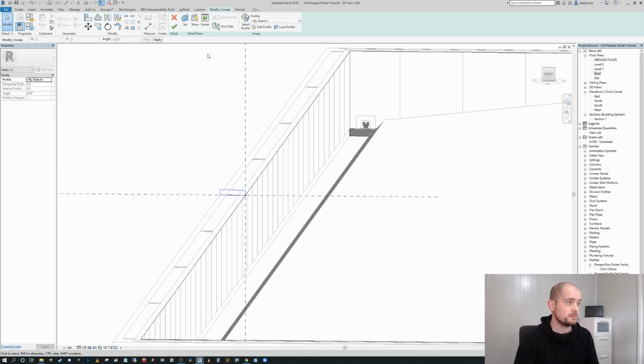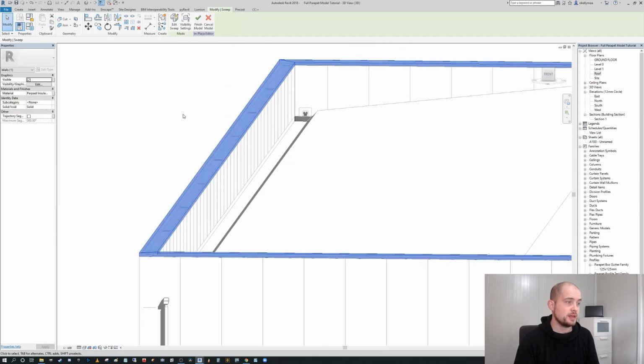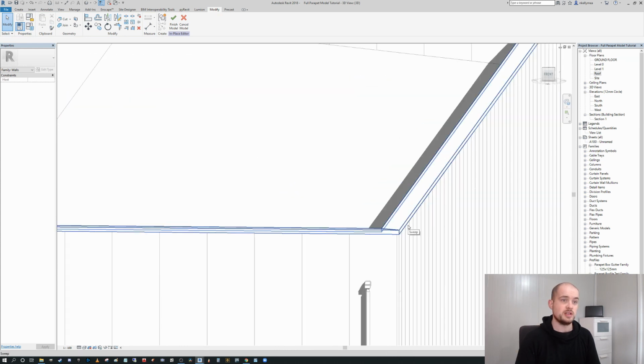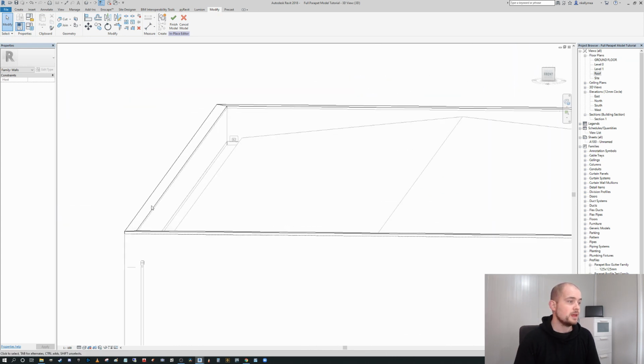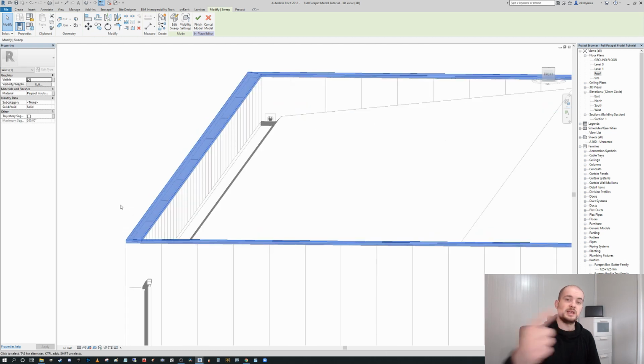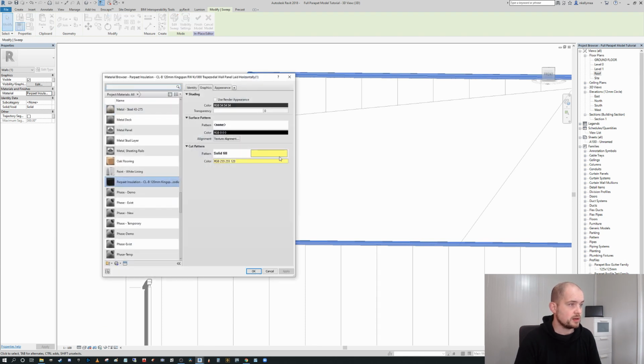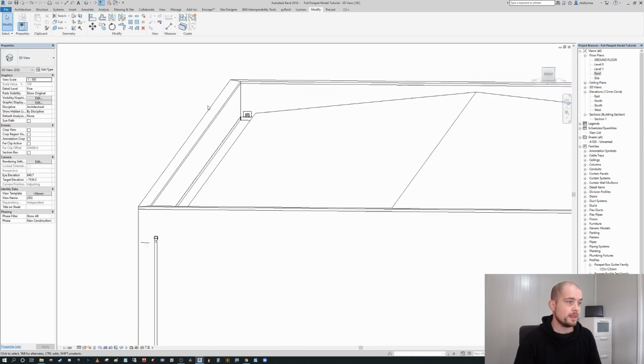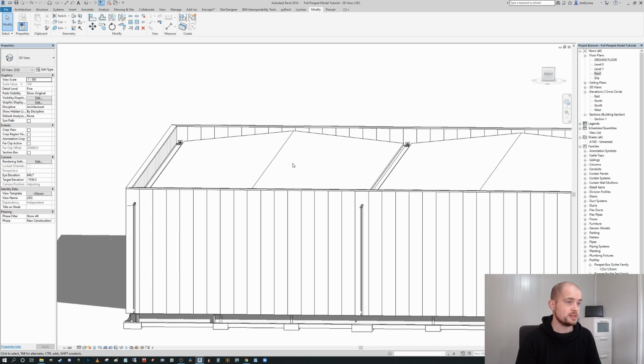So pressing OK, and then going to finish that. And now you can see that we have our full parapet insulation modeled all the way around the suite, okay? Again, because we use the 3D line selection tool on the inside face of our walls, if the grids change, the walls change, this arrangement also changes accordingly, okay? The one thing I want to also do is make sure that we have parapet insulation as our, yes, okay, so we have the correct material assigned, perfect. So I'm going to press finish model there. And now we have our insulation in place for our roof, okay?